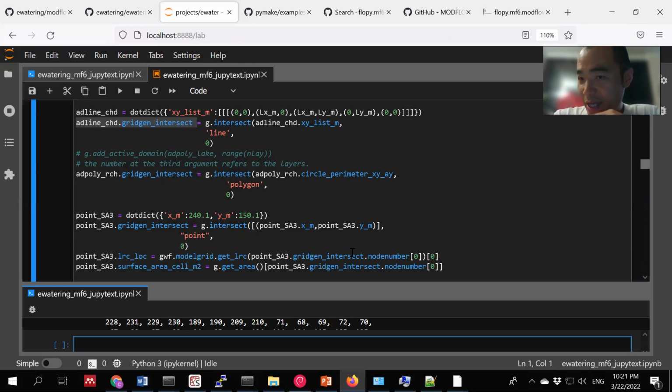And this command is very handy. The reason is that if I want to increase my time and space, this line is able to find out all the cells. So this is not hard coding. I probably can use the first and end to get that, and also I can handily pick some cells, but it becomes very clumsy when you want to change your delta X and delta Y. With this command, you don't really care about which cell is being identified.